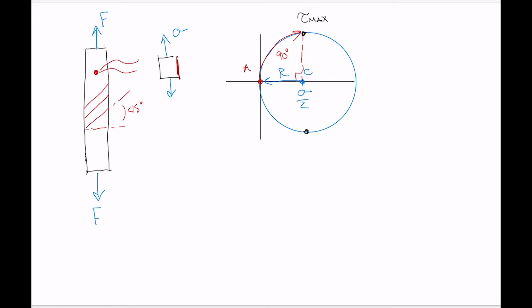So that was the thought behind the fact that it's not the normal stress present that's causing these materials to undergo failure, failure being yielding, but it's actually the maximum shear stress present when the material reaches its yield point.